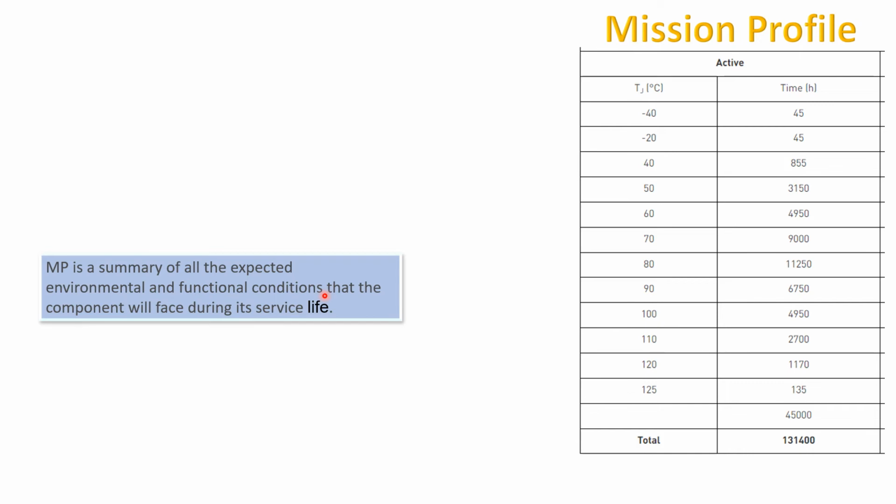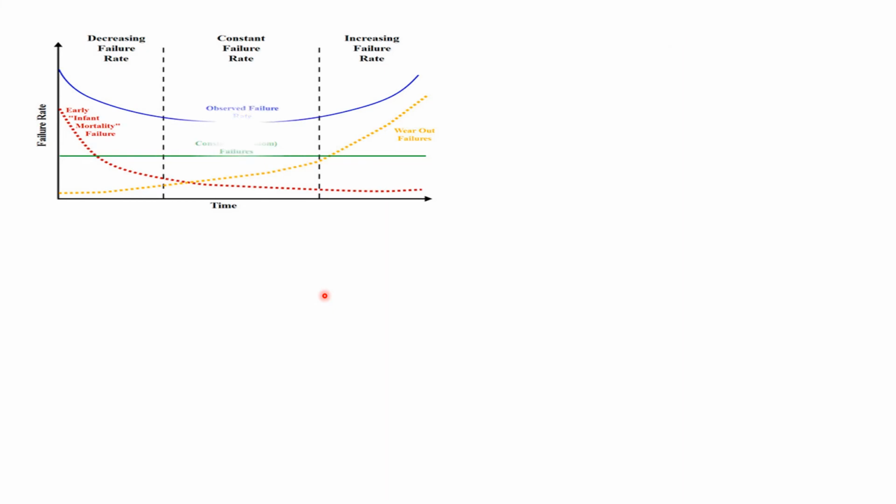Based on this, the number of hours to be performed in HTOL is determined. The HTOL results should be predicted as per the failure mechanisms. Here, since electromigration is the main failure mechanism, we have to appropriately put the accelerated failure mechanism factors in analyzing the device failures, and thus we will get the associated mean time to failure.